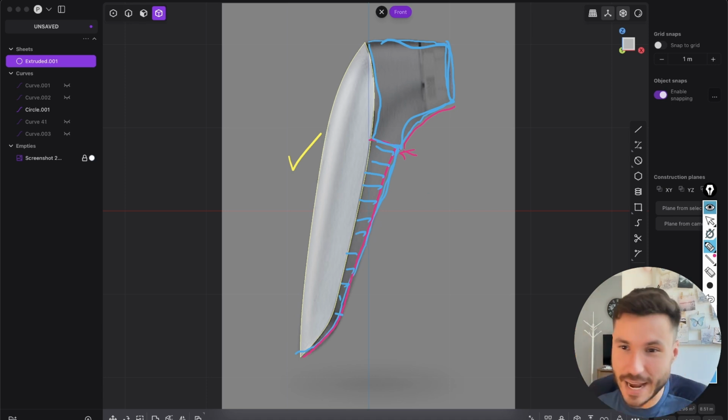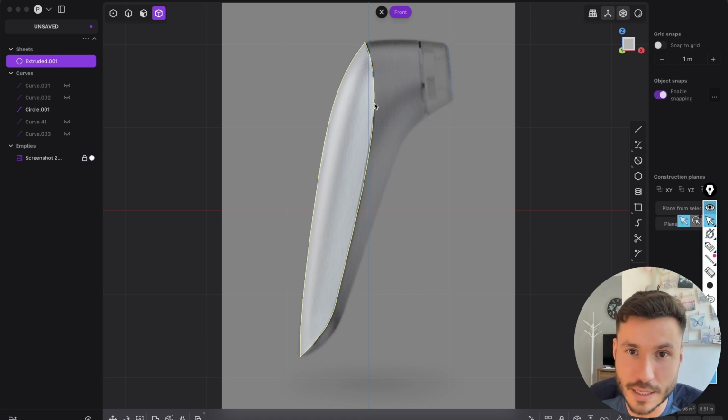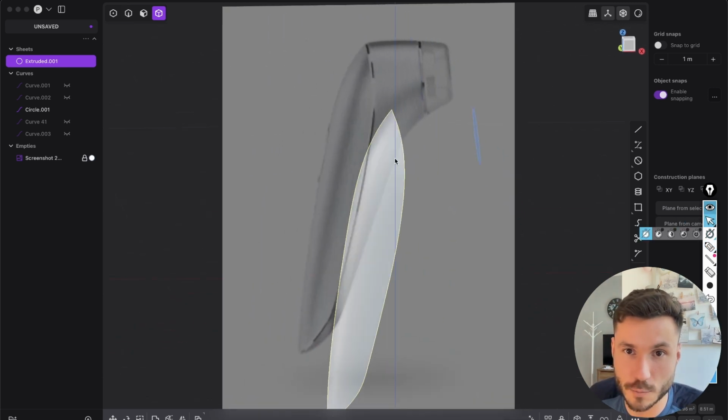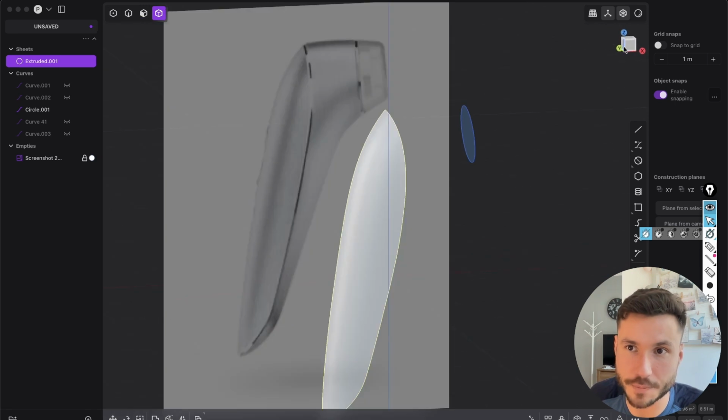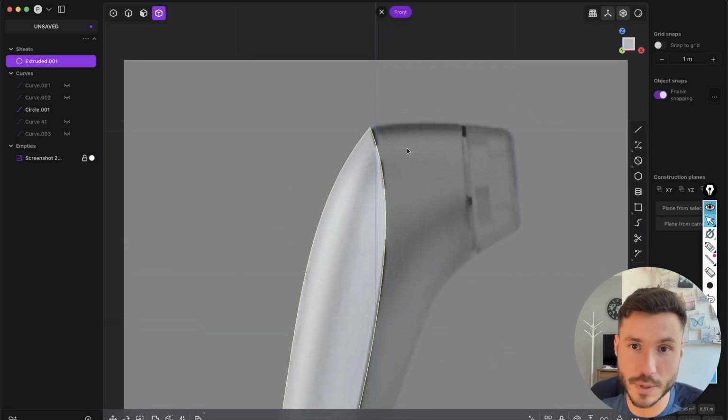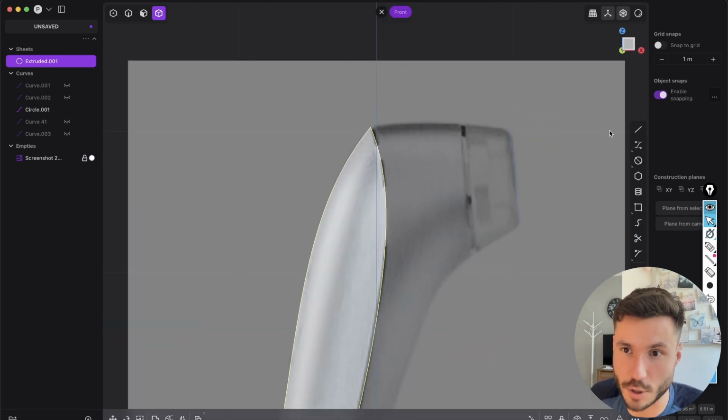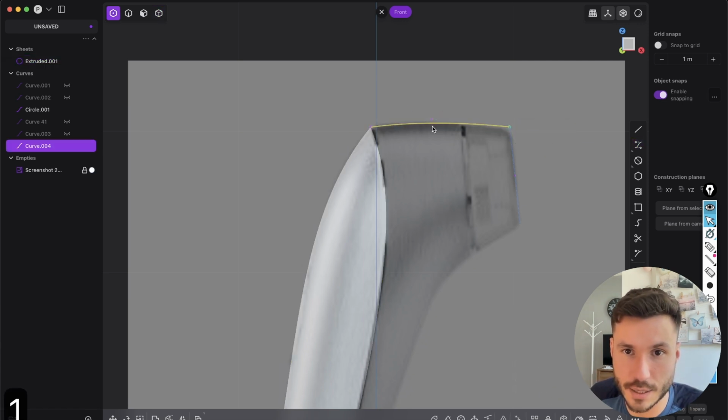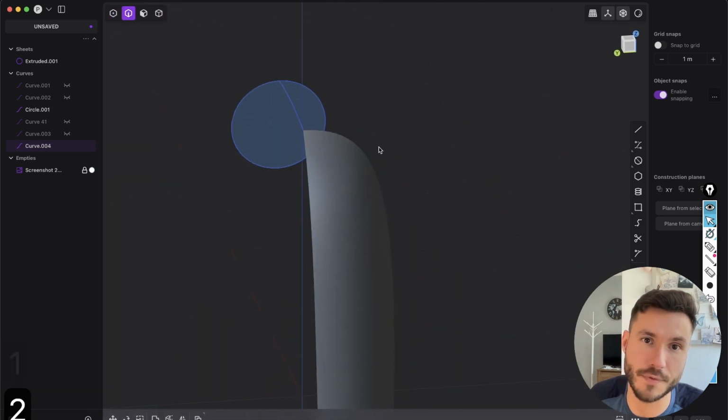It's basically every product, the same approach. Again, let me just show it to you and explain it while we are doing that. So we have our half. And first of all, we can just close here at this top. So again, control point curve and just snap to this point, give it a nice little curve and snap here and just adjust the point, right? So very simple.